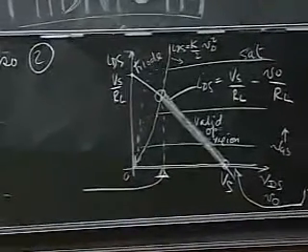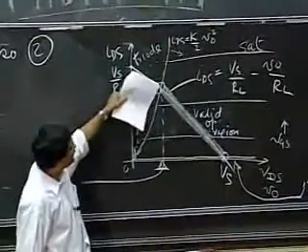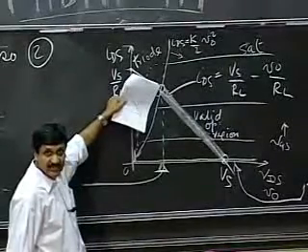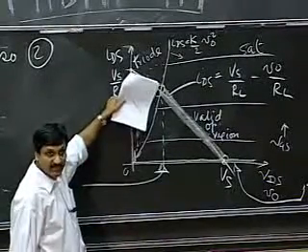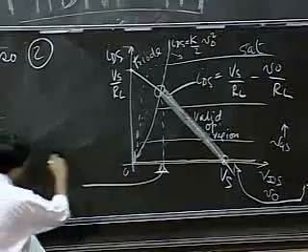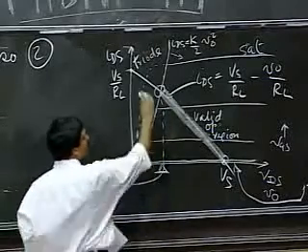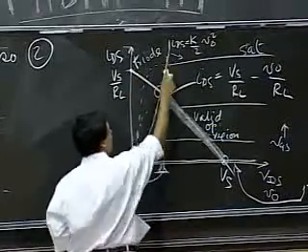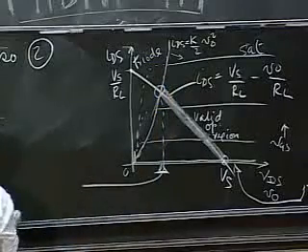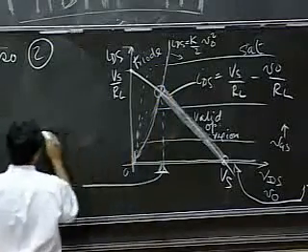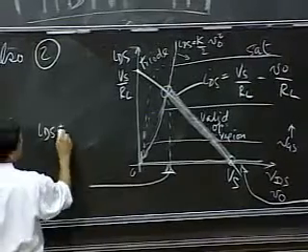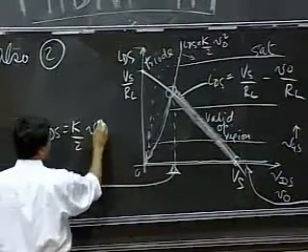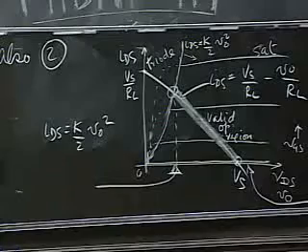And let's find out what this point is. So at that point, I get my output just entering the range of the MOSFET triode region operation. And notice that this point is the intersection of two curves, this line and this curve. Okay? So this curve here is given by IDS equals K divided by 2 V naught squared.